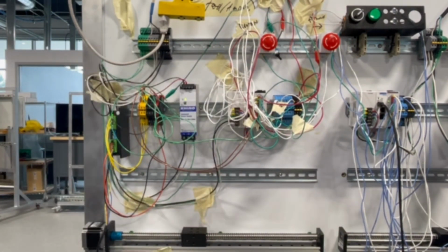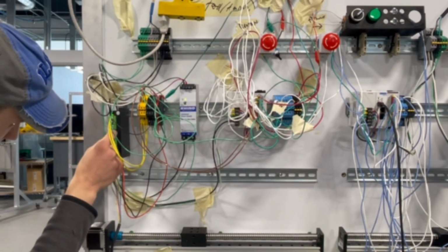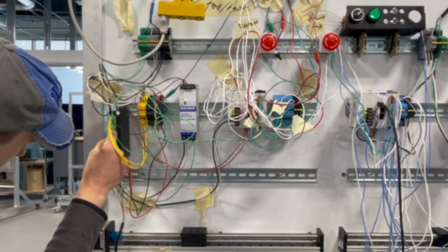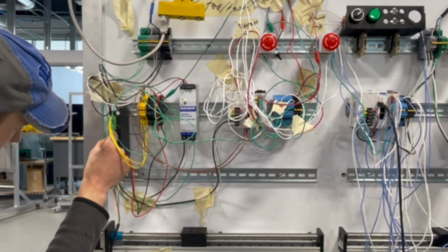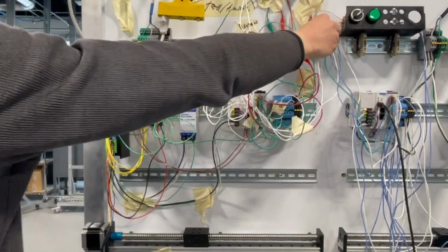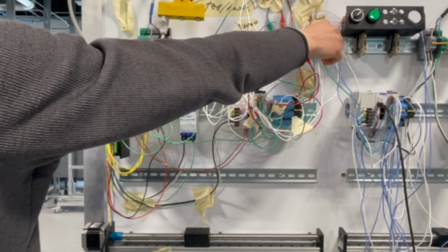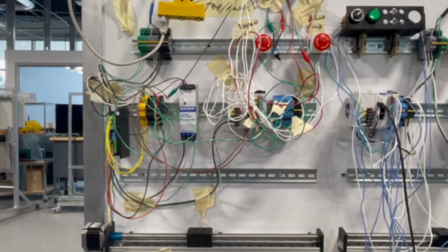Another way to vary the speed is to increase the pulses per revolution by toggling the dip switches on the drive. Following the diagram on the side of the drive, I switched it from 400 pulses per revolution to about 800. This made the motor move roughly half as fast, but much more precise.